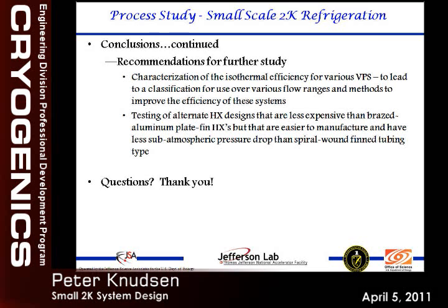So in conclusion, I just wanted to throw up a few things, listed as ideas for further study. Characterization of the isothermal efficiency for various vacuum pumping systems. We don't understand that very well. We know what it is for ours. We have a good idea for ours, but for a general vacuum pumping system, we don't really know that well. That's also hard to quantify because some of that information is going to be proprietary. But it is very key to doing a process study like this.